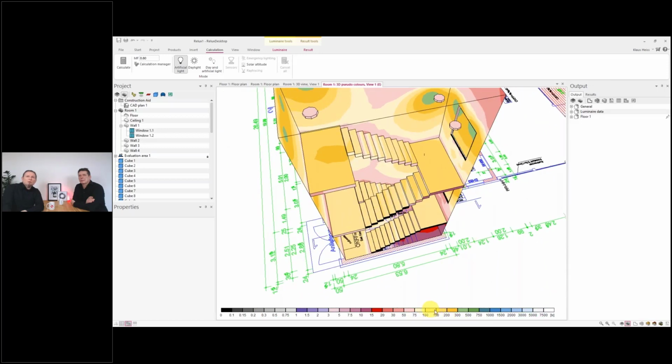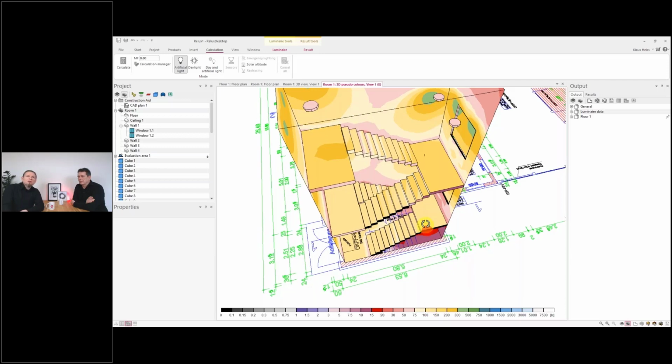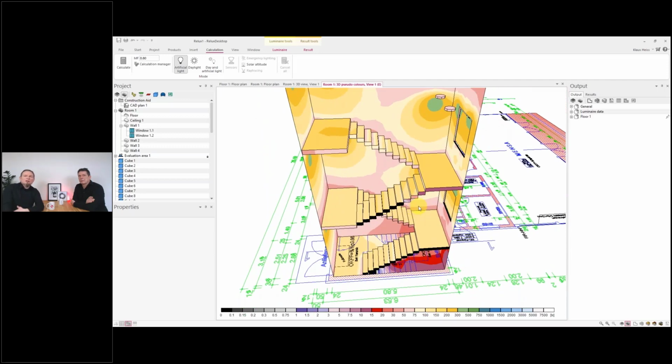We are in the area of 100, 150. This is a nice staircase, at least in Europe. In 12464, we have 100 lux as a minimum for a staircase. Of course, you can add more to it, so 150 is also quite common. There was an old 12464 with 150 years ago, I guess. Maybe just for schools. Something else, but this is nice for illumination levels.